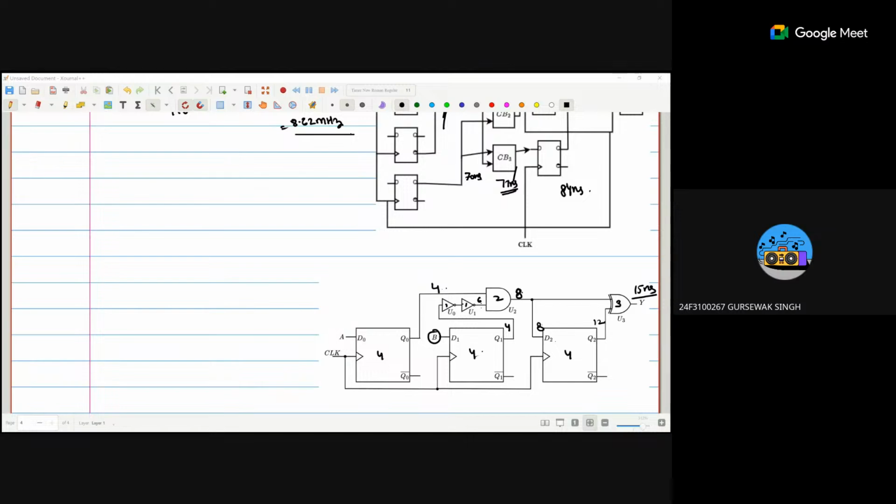But after that, I was thinking about it the other way, like how to get 11 nanoseconds. This is a Moore machine, right? The output doesn't depend on the input. They're asking after the clock edge, right? So when U2 arrives at D2, at the first clock edge, it's invalid for 8 nanoseconds. Then D2 is valid, and at the next clock edge, Q2 appears. So at the second clock edge, Y appears after 11 nanoseconds.